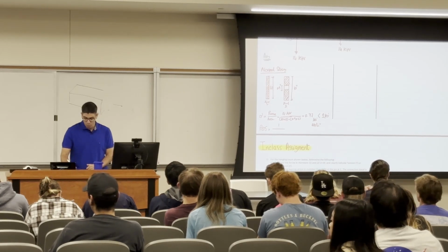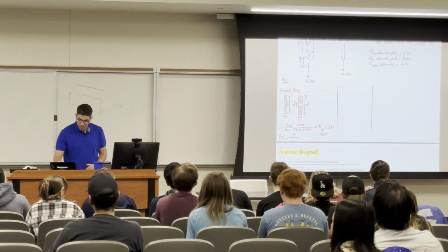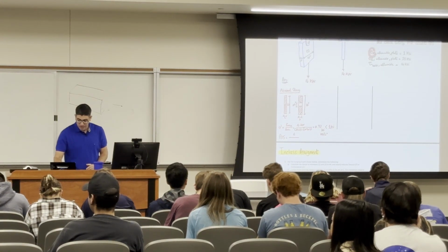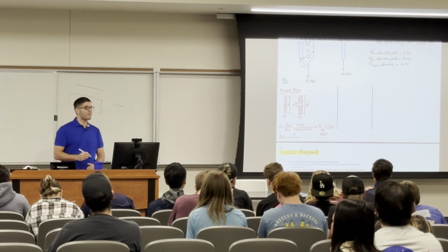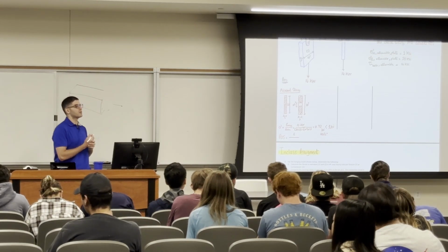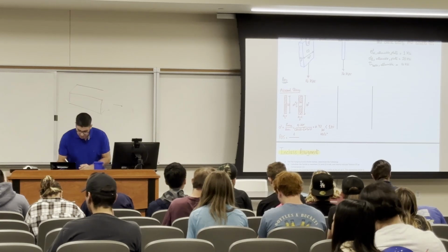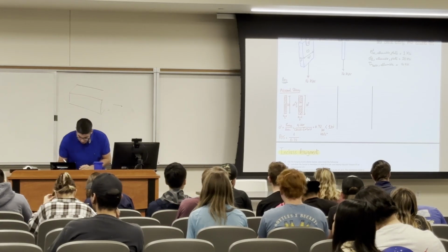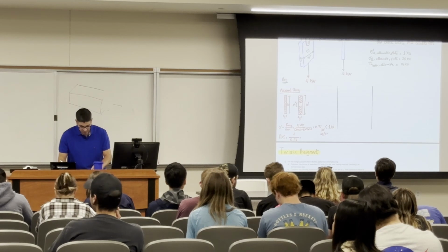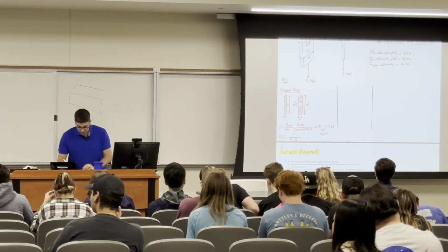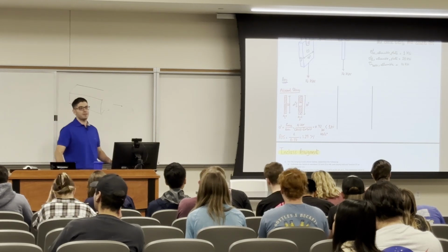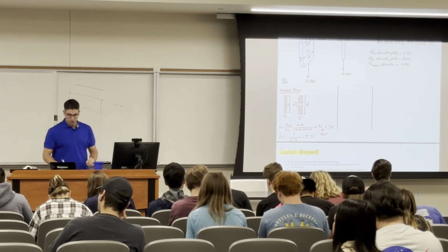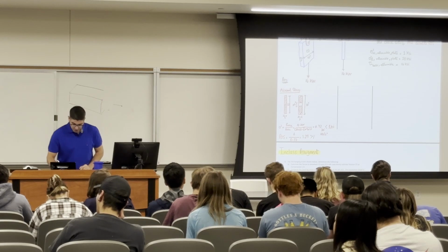Okay, the capacity is 1, because that's what's allowable here. The normal stress allowable for the plate is 1 KSI. So I'll put 1 at the top. What is the demand? What am I demanding here? 0.7. So I'm safe by how much? 1.29. As long as it's greater than 1, then I'm fine. I'm happy.